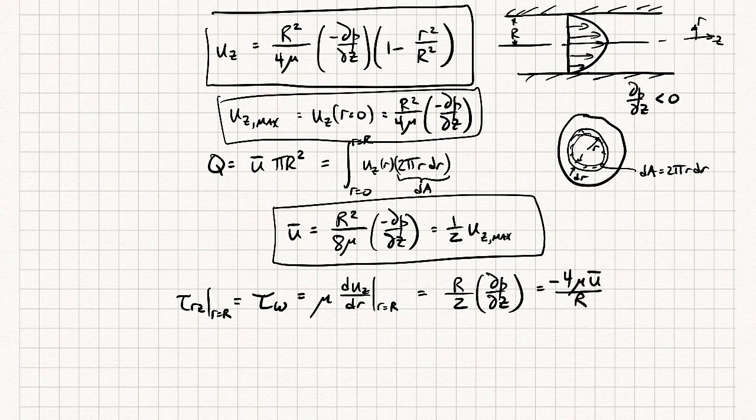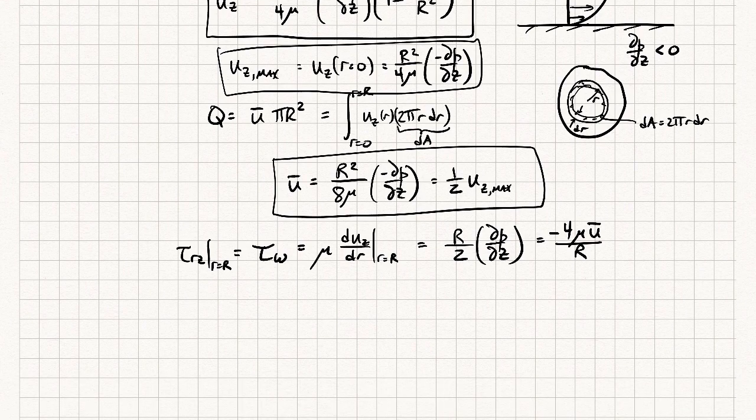The reason I've written it down this way is because we're going to make use of that a bit later in the course when we start talking about pipe flows. In fact, what we'll end up doing when we deal with pipe flows is we'll write out a dimensionless wall shear stress. What I mean by that is we'll just take the wall shear stress and get rid of the units of it by dividing through by the dynamic pressure in the pipe. Remember that dynamic pressure is like 1/2 rho v squared, but I'm making a dynamic pressure based on the average value of the velocity. So I'm just making this dimensionless. And for historical reasons, people multiply the numerator by a factor of 4. That's just historical. It doesn't change the dimensions at all, but they just put that in there.